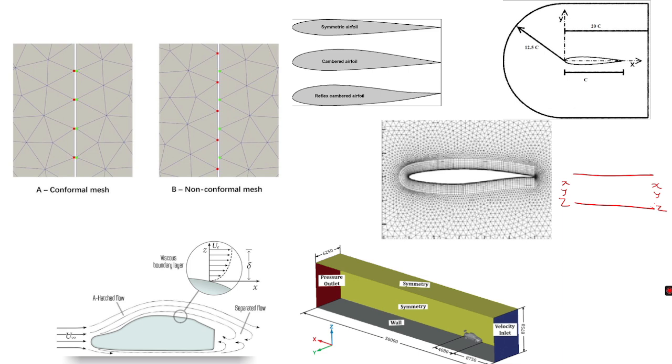Channel flow, if we take the example: simulating the flow in a long channel without modeling the entire length. Lattice-like structures: analyzing the repeating units of a porous medium or heat exchanger. Turbulence simulation: capturing the small-scale periodicity in turbulence studies. So these are some points we need to remember about periodic boundary conditions.